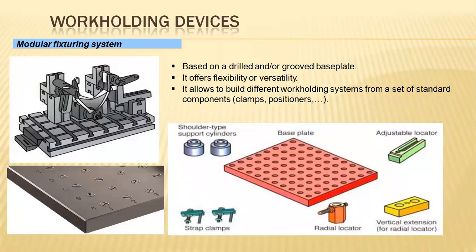Coming to the work holding devices in the case of the modular fixturing system. So modular fixturing system, in the sense, is based on a grooved base plate or else a drilled base plate. Grooved in the sense will have particular representations with respect to different significations.